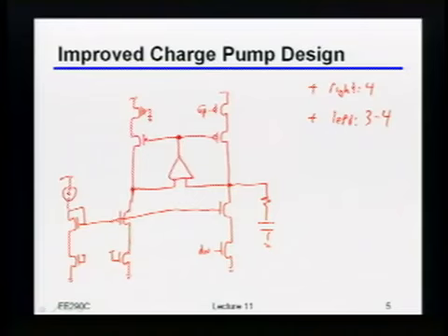So, can you arbitrarily move this voltage around, given that there's a PLL feedback loop? Or no? You can't, right? Ideally speaking, the PLL makes the impedance of that node 0. Right? Because that voltage has to be whatever it is to get the frequency right. Okay? So now you guys tell me, where do you put the plus?